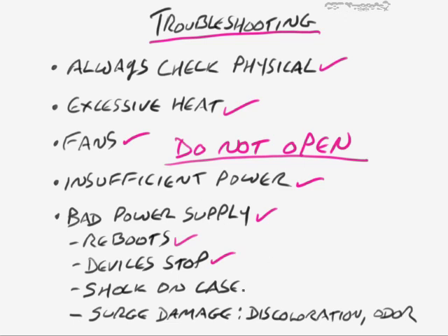Here's another thing, and this might sound almost like a joke, but when you touch the case, if you get an electric shock, now, I'm not just talking about static shock that happens sometimes. I mean, you actually get an electrical current that passes through you. You know, stands your hair on end. If I had any hair, maybe it would stand on end. Well, this again is a potential symptom that the power supply has gone bad, although in my view, it's probably more likely that there's something that's touching the case that should not be.